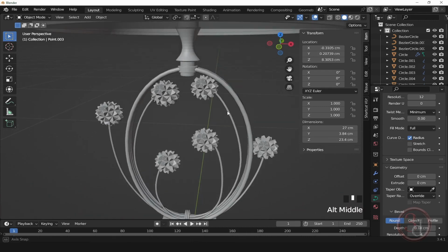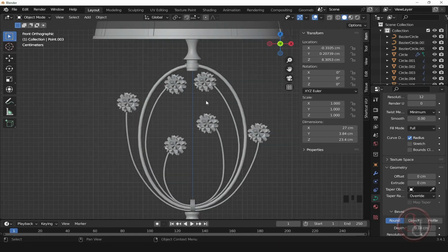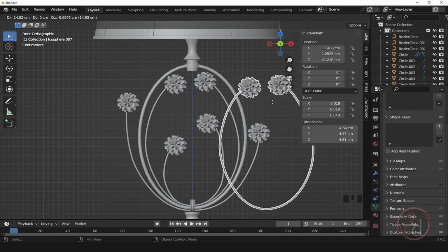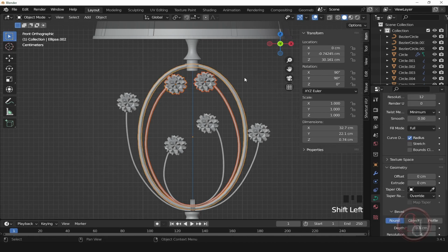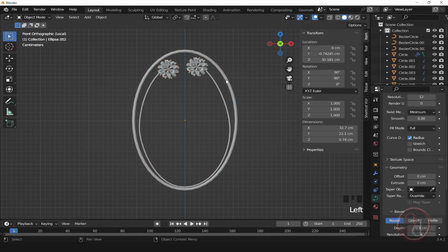Okay, and just one last I will create from the front view. So again I will duplicate this one, Shift T to duplicate, right click, it is selected, and I will isolate it. So what I will do is, for now I'll just shift select one of these and press the slash. Okay, so now I can easily modify it without confusing it with the existing one.